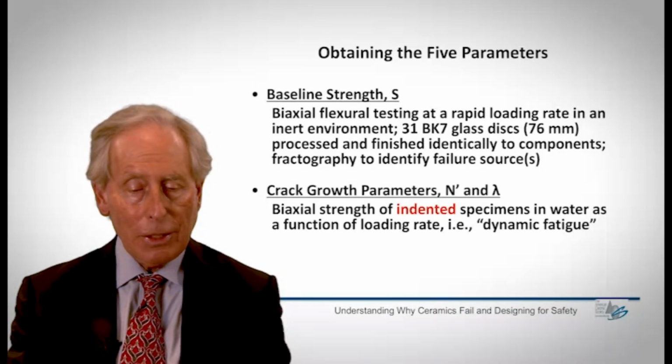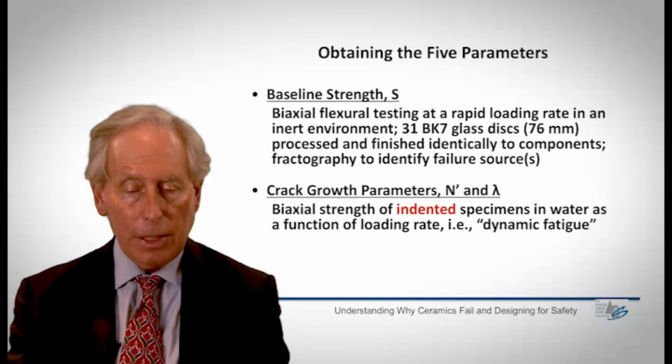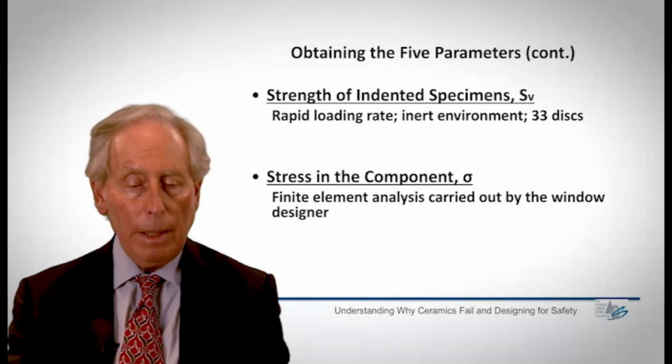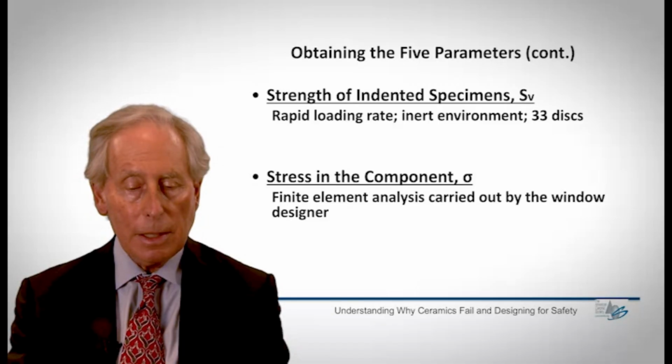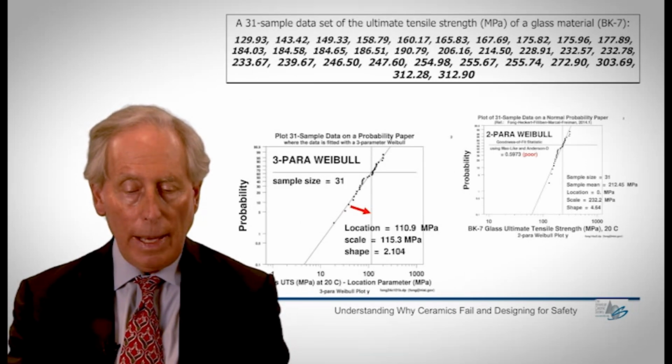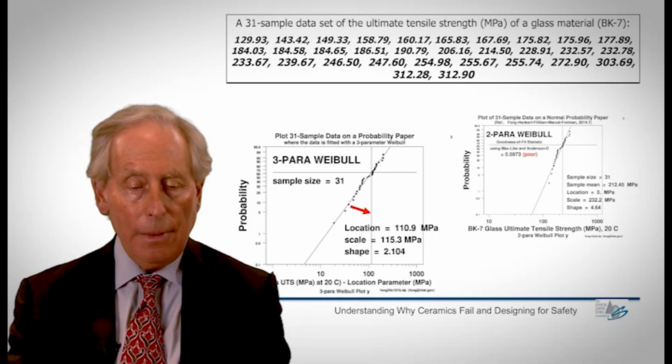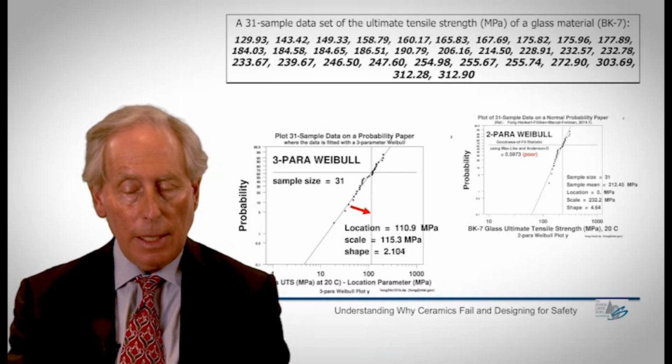We measured the biaxial strength of the indented specimens in water as a function of loading rate to get the dynamic fatigue data, and I showed you that data a little earlier. We measured the strength of indented specimens at a rapid loading rate in an inert environment. In this case, we used 33 discs. And the final analysis carried out by the window manufacturer gave us the stress in the component. So in principle, we had all of the data we needed, and this is all the data you see here.